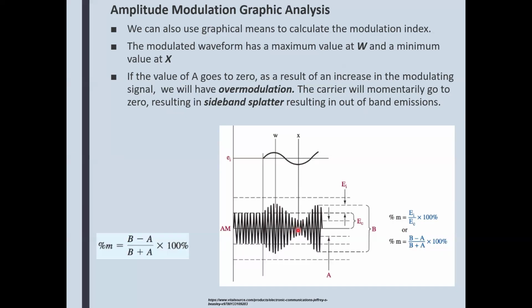So if we're over-modulating the carrier, you're going to see a dead space between those bumps. So you want to have it going down to 0 as much as you possibly can, but not splitting the envelope, because this here, that is called the envelope.